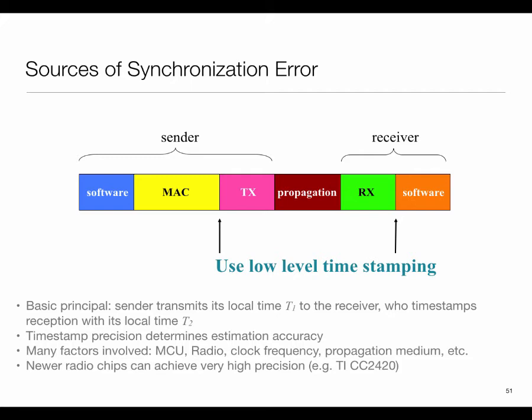Okay, so the preferred way of time stamping, therefore, is not to use the interrupt handler, but to rather use this shadow capture, shadow register or capture register, as they're called. But how to specify the criteria at which this timer capture will happen? The criterion would be by tying the pin. So associated with the timer would be some pins that timer is able to monitor. So you will have to make sure that the relevant signal of your radio is feeding into one of those pins, and then the processor would have some sort of a control register in which you specify that whenever that pin has a transition, then this timer's value should be saved into the shadow register, okay.